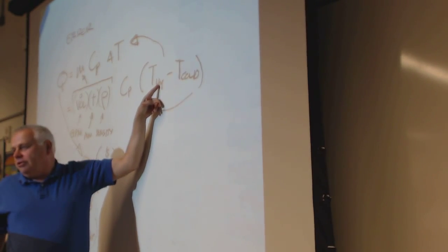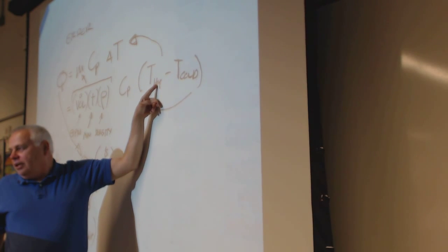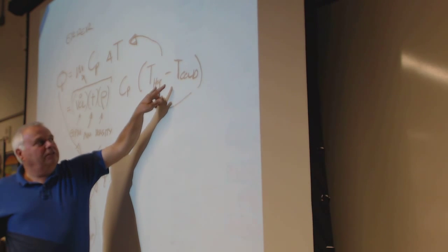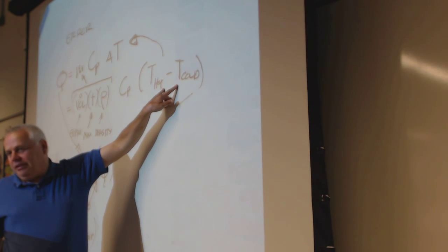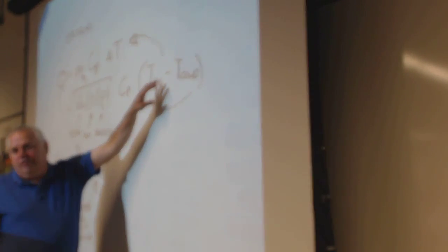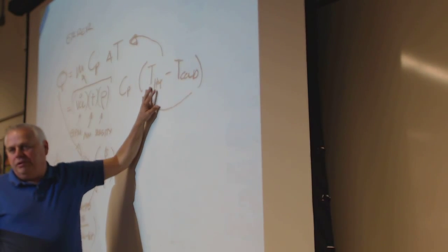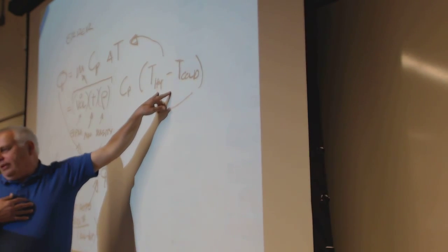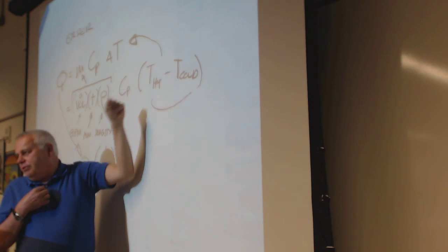If this was a 50-degree temperature difference, from 54 to 104 degrees, 104 is about a hot tub temperature, and this is plus or minus 1 degree, it's not 1 degree out of 104 degrees. It's 1 degree out of the 50 degrees. That's like a 2% variation. If it's 2 degrees, then out of a 50-degree temperature difference, not 104 degrees, you're talking about plus or minus 4%.